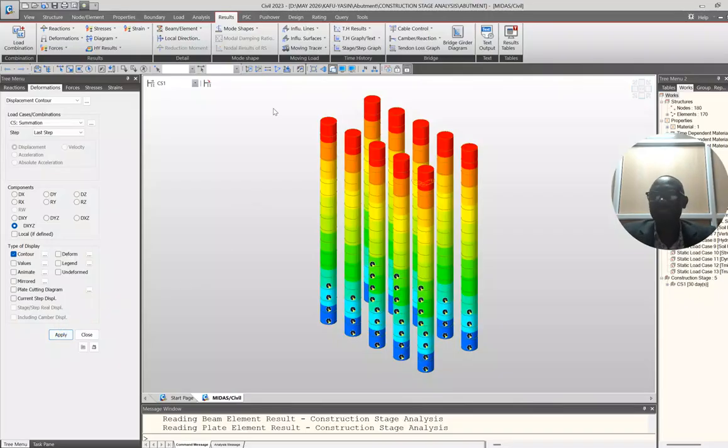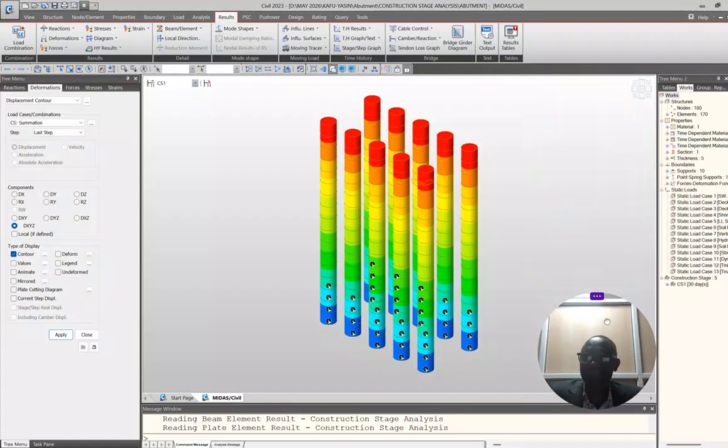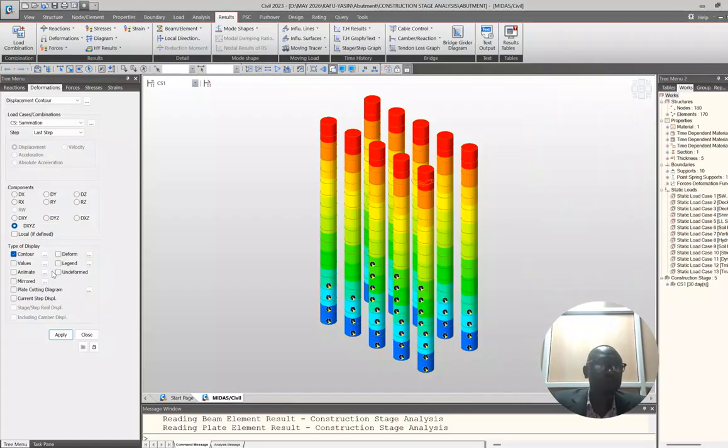So this is the self weight of this pile, when you have now inserted the piles. Then of course at the moment, at the construction stage, this is not what you have. And what I would have done is to have this spring constant all the way up here, and then the second one I would now bring in my pile caps.